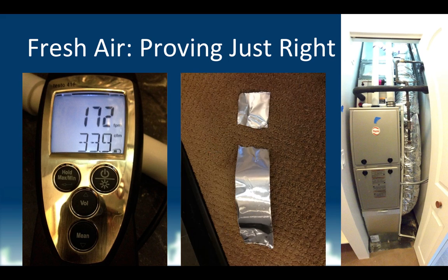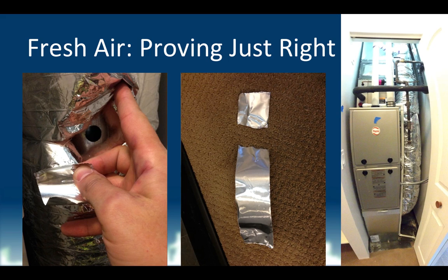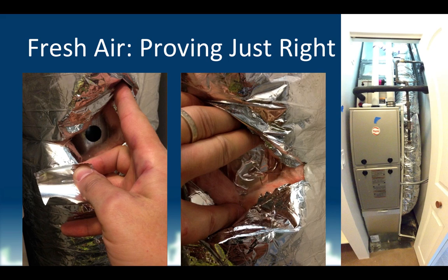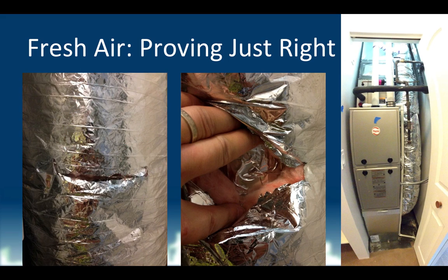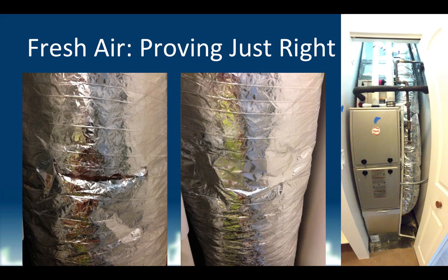Now I have to seal up the holes. So I have to take 2 pieces of tape. Little one, big one. Little one, I put right over the actual hole in the duct, inside there. Now I can basically smooth out all the insulation so that it's nice and even and cover up the slit that I made in the insulation with that long piece of tape. And now it looks good as new.